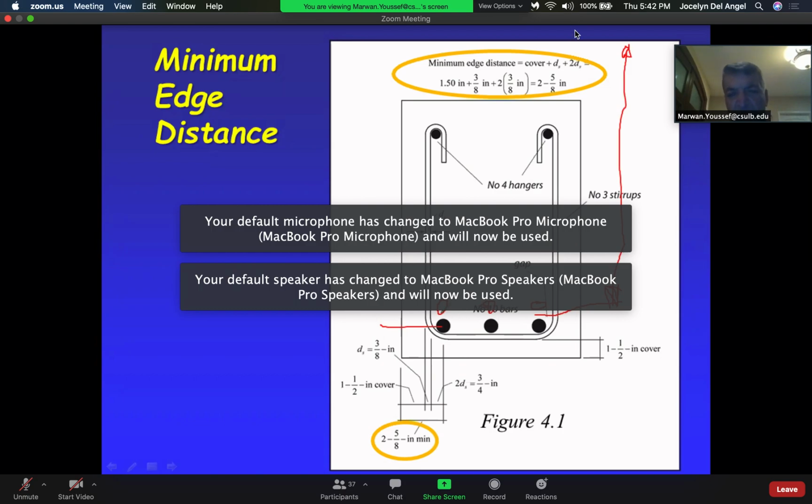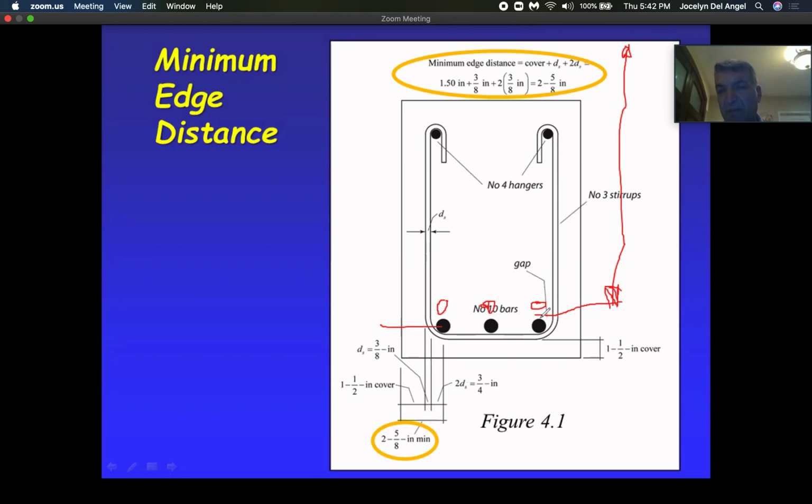Center line between. So how much is this spacing you think between the two? It's going to be either the diameter of the bar or 1 inch. Let's say it's 1 inch, right? So this is going to be half an inch above. You can have 3 layers, by the way. I would not go more than 3 layers.